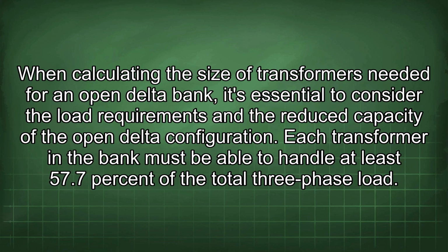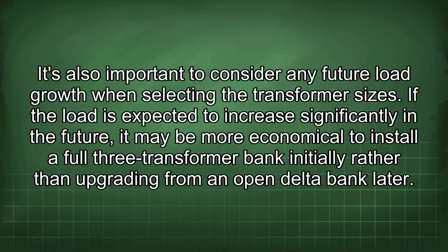When calculating the size of transformers needed for an open delta bank, it's essential to consider the load requirements and the reduced capacity of the open delta configuration. Each transformer in the bank must be able to handle at least 57.7% of the total three-phase load. It's also important to consider any future load growth when selecting the transformer sizes.